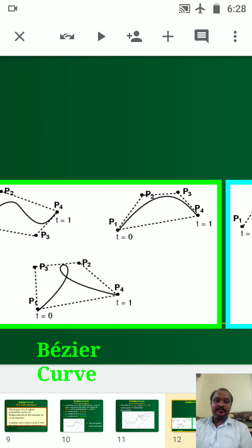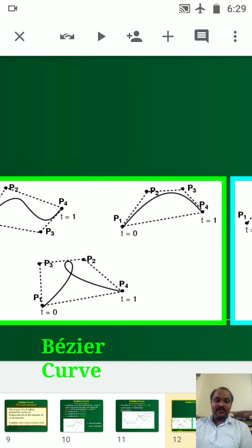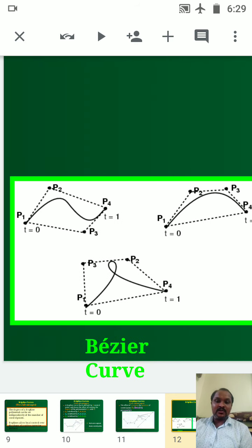In the second diagram, the same thing, it is a continuous simple parabolic segment. At the initial point we have the tangential line, again at the curve segment we have the tangential line, and at its end point we again have the tangential point. We are just adding the control points directly with the line segment, that is P1, P2, P3 and P4. But here also the parameters, T is equal to 0 and T is equal to 1, mean the parameter points will be only 2. In every diagram we have only the first point and the end point.